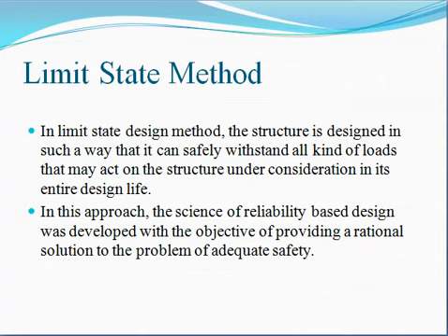In this method, we have to use the partial safety factors to account for all uncertainties. See, in the limit state design method, the structure is designed in such a way that it can safely withstand all kinds of loads that may act on the structure under consideration in its entire design life.